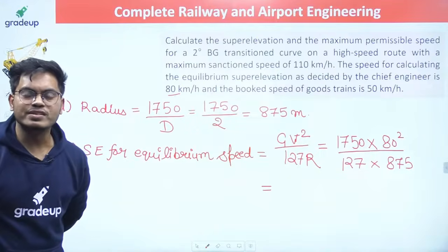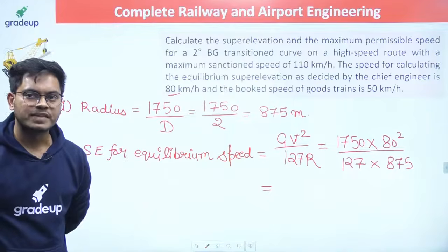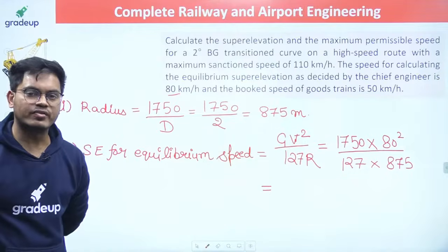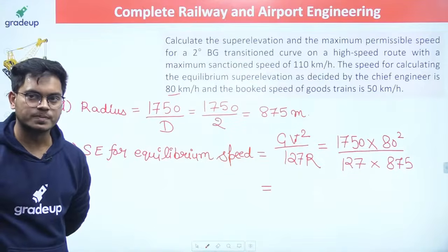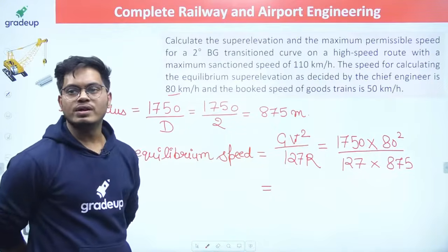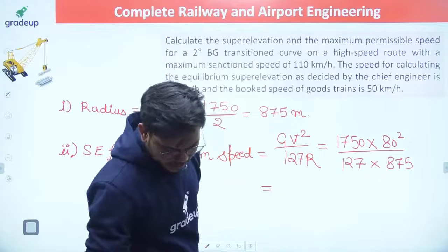1720 or 1750, sir? I've already explained this. That is dynamic gauge, 1750. And 1750 is when we are considering 100 feet chord, that is 30.5 meter. So yes, very good. I have got no answer till now. Why is that happening? It should be 100.8 mm.